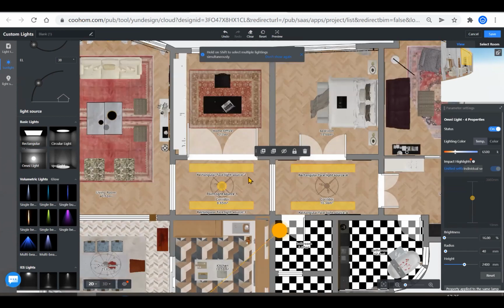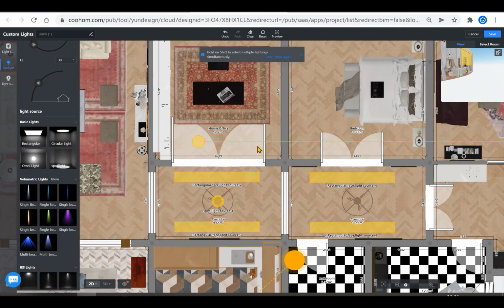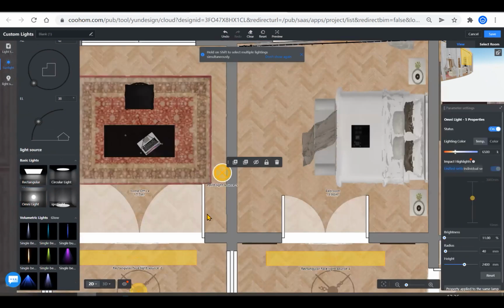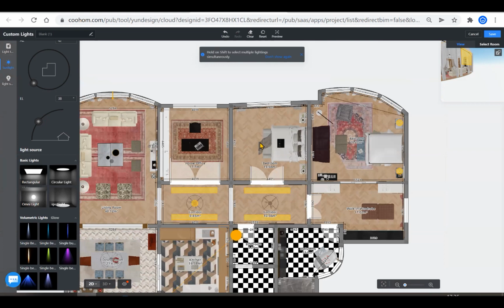And also, one suggestion: when you add some compensate light or, let's say, omni light, do remember not to put it overlapping with the wall, even if it's for a spotlight or something. If it's for a downlight and it's overlapping with the wall, it will be cut down by the wall. So the light effect will have some small bugs. So that is one thing I would explain.